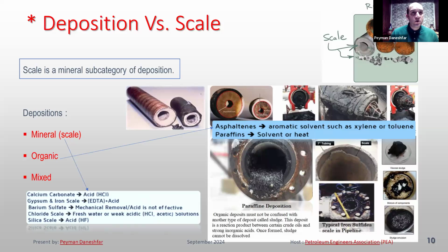When you confront calcium carbonate, you can dissolve it with HCl acid. When you have silica scale, you can dissolve it with hydrofluoric acid. Some other scales you can see in these slides, and I think you can take a picture of these slides, whichever you want to keep in your mind.